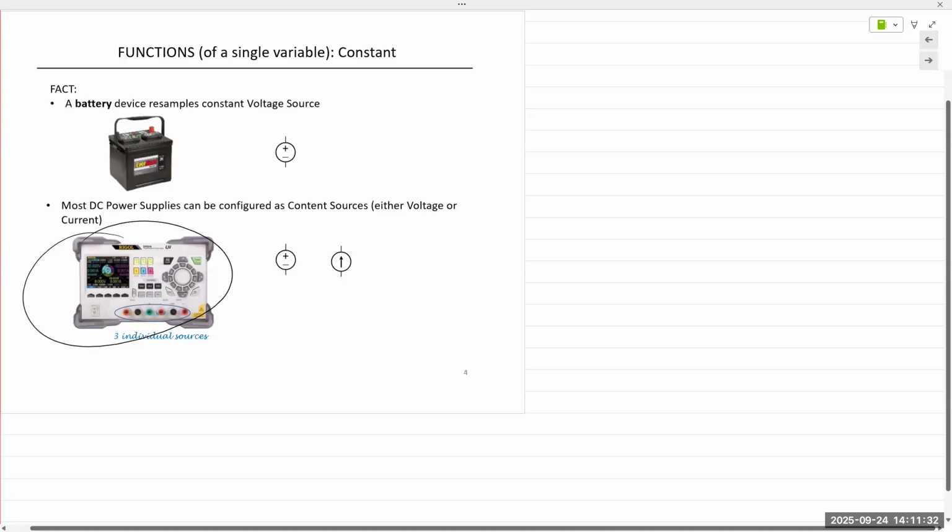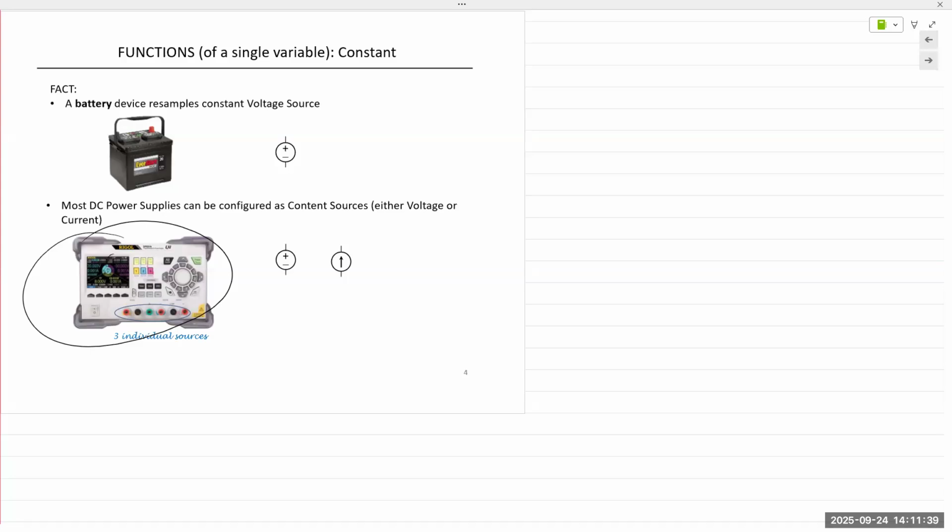All right. It's very hard to see. Obviously, it's nearly impossible to see, but I think right there at the top on these power supplies, it shows you CV. So it's either CV or CC, constant voltage or constant current mode, right at the top. And other models would be slightly different, and they would also have some notation somewhere.